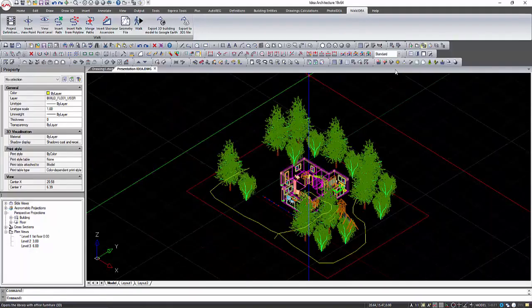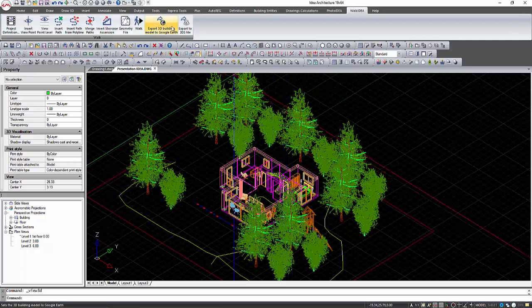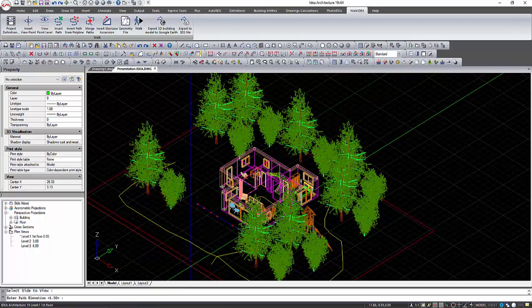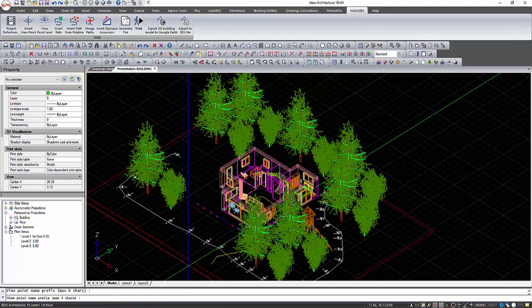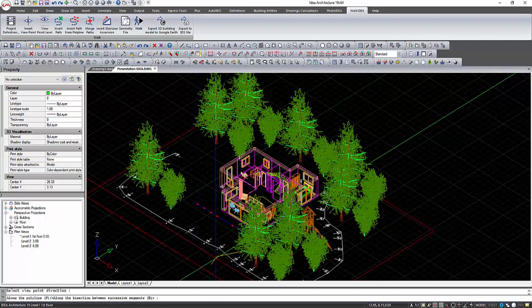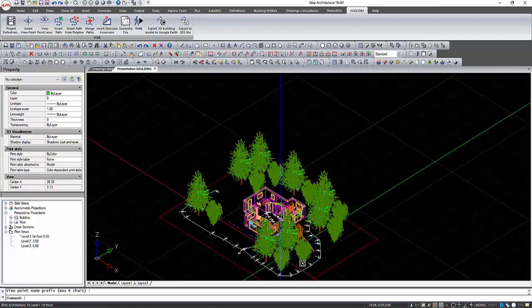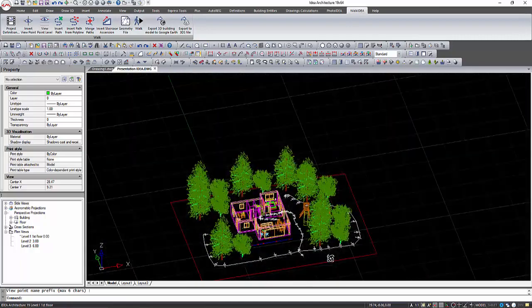We switch to 3D view. With the command insert path from polyline, we select the first polyline. We set the option B, to set that we walk looking to the bisection of the segments and not along the polyline. Giving the rest of the settings, and the visible side, the path is displayed. In the same way, we give the options for the second polyline and now, both of them are displayed in our model.